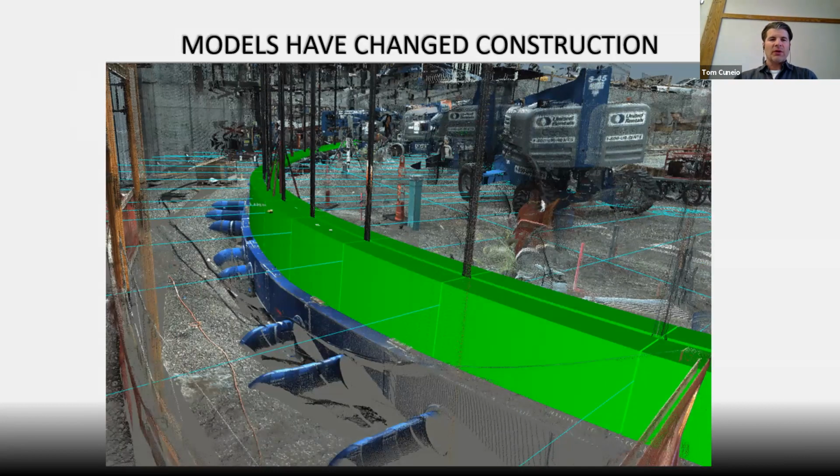So there's a forward-looking kind of future component to this. This is a laser scan. So using LiDAR, we're scanning projects at some intermediate state of construction. So we're capturing as-built from other trades. And then we're taking materials that are maybe still in production that are going to come to the job site, and we're checking them for fit. Do the trades that have come before masonry, for example, have they executed well enough that we're not going to have issues? If they haven't, we have time to modify a production order and avoid the waste that is part of traditional construction.